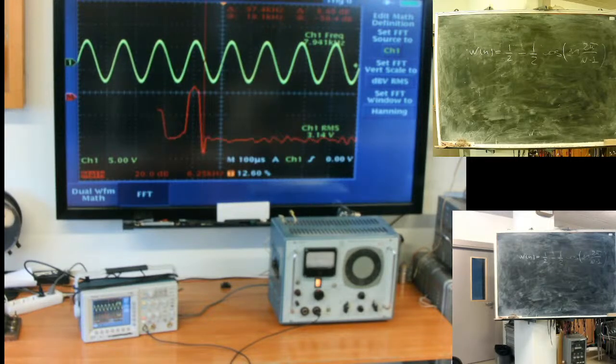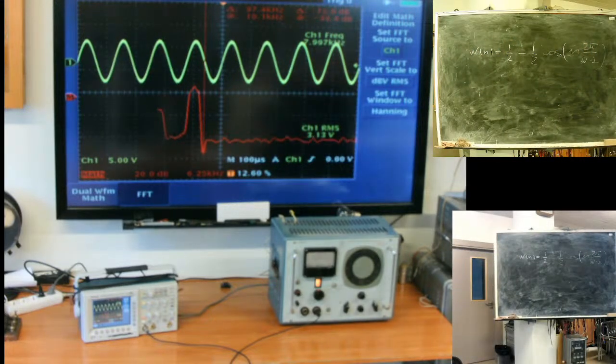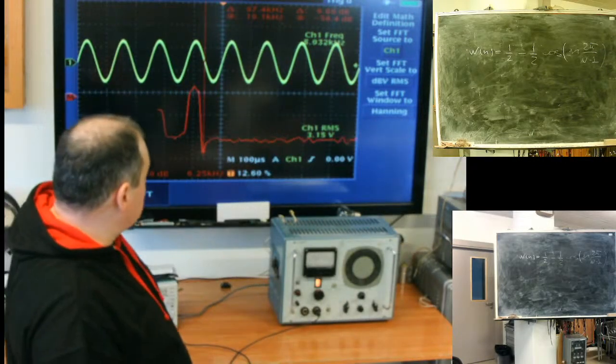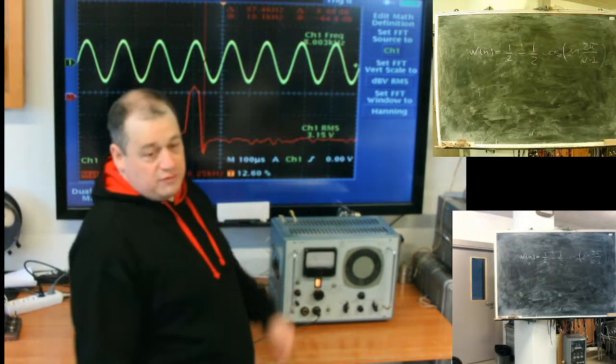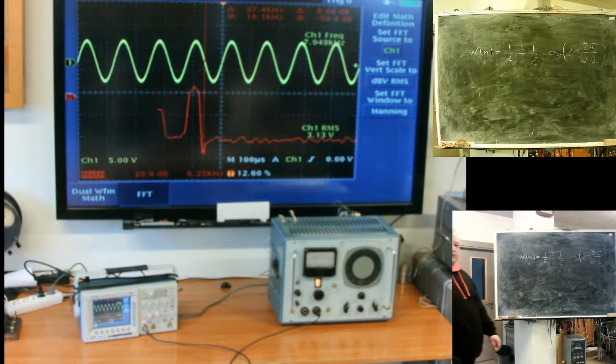With the observation window, sometimes a bit of magic, or magician's work, is required to select a proper window, because you need to find a balance between frequency resolution and the level of side lobes, which limits detection of small signals. Yeah, I think it's okay for today.